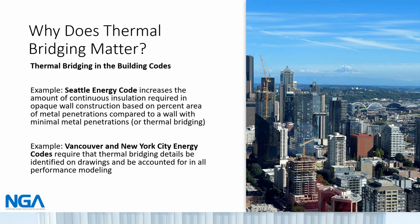For example, the Seattle Energy Code increases the amount of continuous insulation required in opaque wall construction based on percent area of metal penetrations compared to a wall with minimal metal penetrations, or thermal bridging. Energy codes in Vancouver and New York City require that thermal bridging details be identified on drawings and be accounted for in all performance modeling.